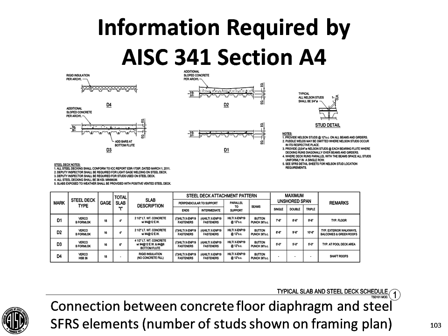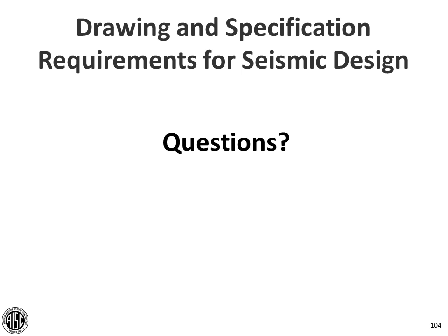And then the last thing is that there's a requirement that the connection between the concrete floor diaphragm and the steel seismic force resisting elements need to be shown, and in this case this is being done through the use of the shear studs, and the number of studs are shown on the plan, and the details here show how those would be located within the deck itself. And so that finishes my portion of the presentation. I'll turn it back over to Christina.